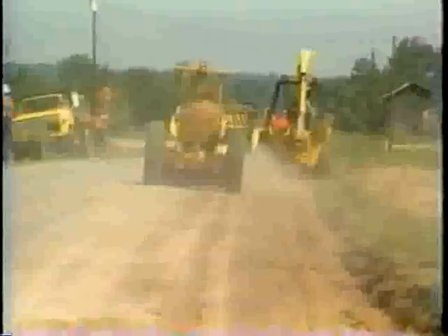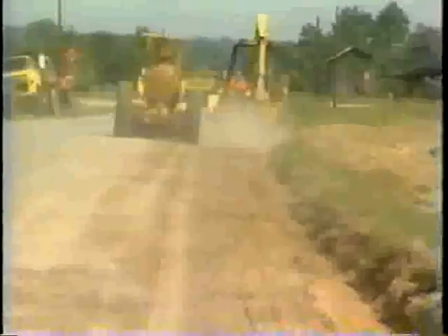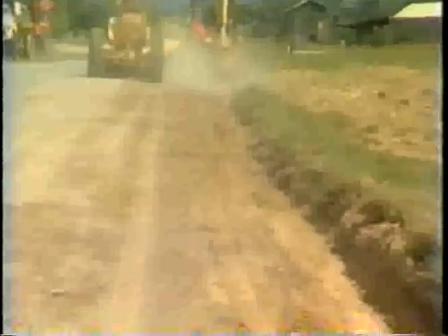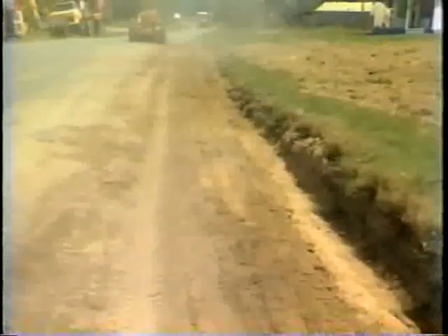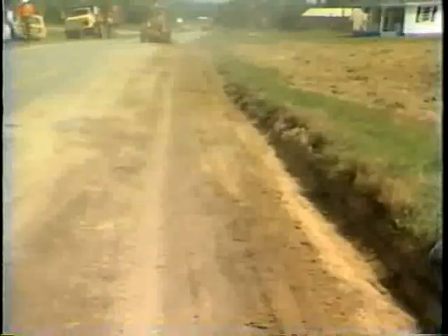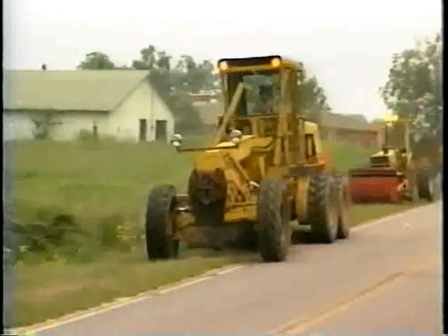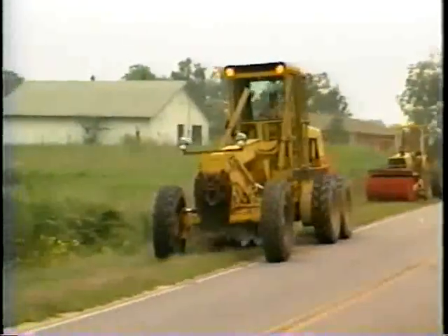If necessary, broom excess material off the pavement with a power broom. The repaired shoulder is flush with the edge of pavement. No buildup remains. Place seed and mulch as needed to reestablish vegetation on the unpaved shoulder. When high shoulder repair is performed on a filled section,